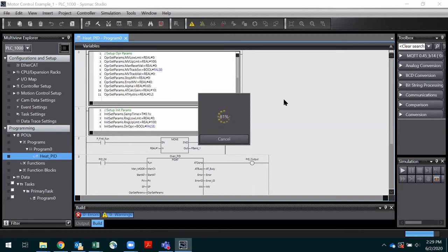Do you want to maybe try a branch around that move so that the P first run also sets some kind of latching coil, just to see if the P first run ever even does turn on? Yeah, good point. It almost looks like there's an issue with execution, like that whole section may not be executing. It is the whole section, yeah. If you look up at the structured text section where we're writing constants, the variables don't get new values. Right. So yeah, it's definitely an execution thing.